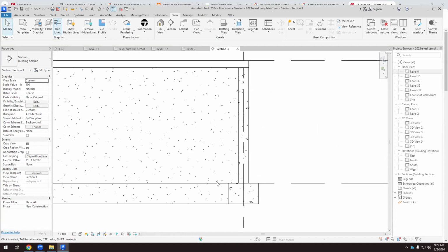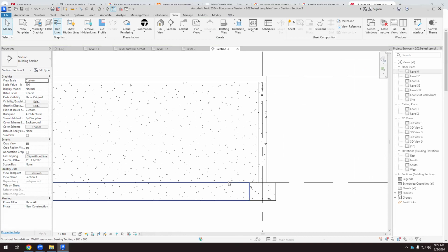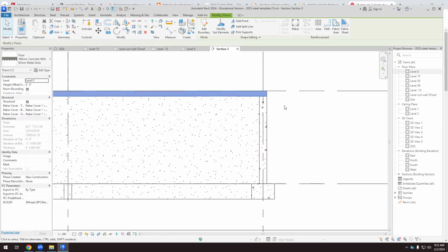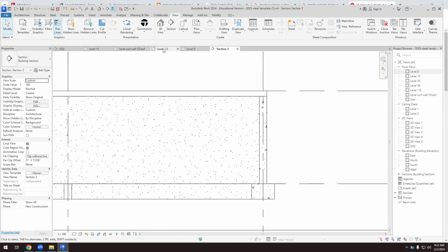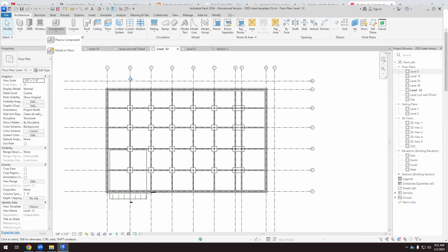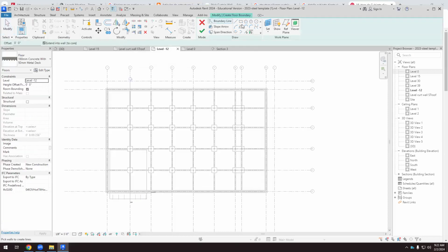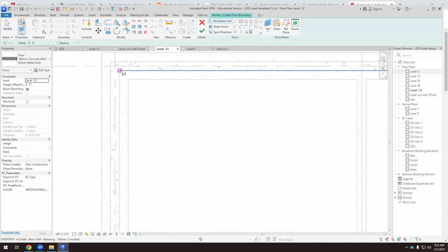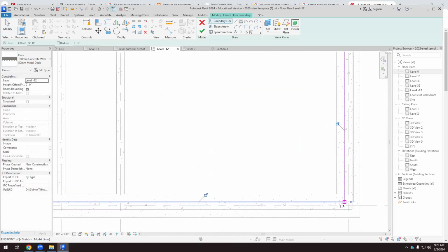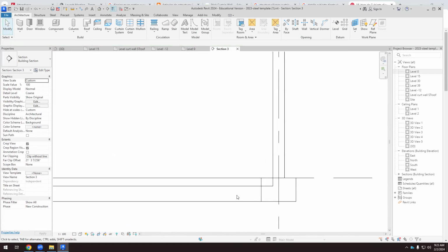Okay, so we created all the basement, but we don't have the floor slab. We have a floor slab here, the ceiling of the basement, but we don't have the basement floor. So I think the first thing we have to do on level -12 is go to architecture, not component, architecture floor. And I just want a rectangle from this point to that point here. I click OK, I go back to the section, and this is what happens.